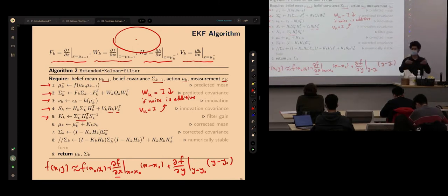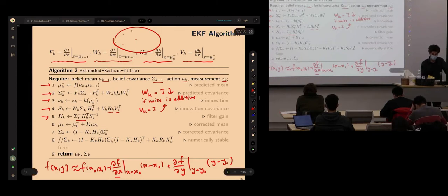That means if you take 1,000 measurements and then take the sample mean, it gives you the correct answer. It's not, let's say, biased, right? However, if it's biased, because each time that bias will appear in some way, if you take the sample mean, that won't be a good value to work with. So that's why it's very important to compensate the bias of the sensor, offline or online. If the sensor is imprecise, that means in the limit you can get correct answers from that sensor.